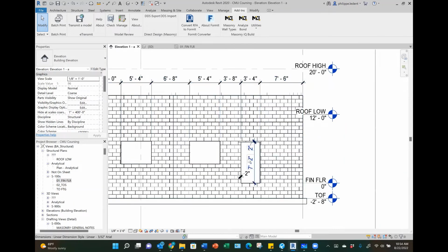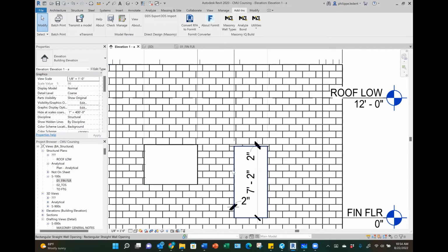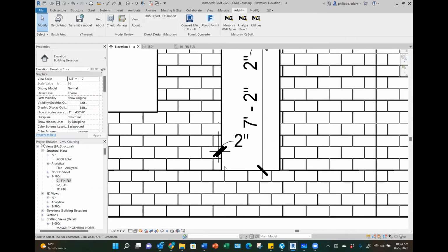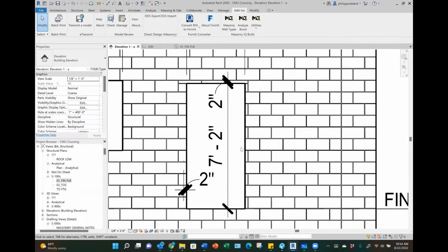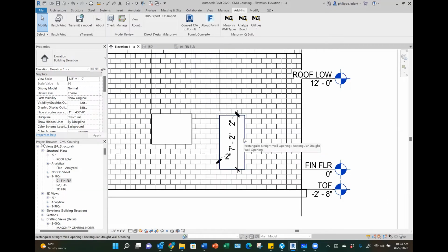Additionally, I had moved this door specifically to show you the impact of overall dimensioning. I offset it from this window 3 foot 8 inches, which looks like a modular dimension with that 8-inch number. However, if we look at this door, they would have to cut all these units on both sides of our door in this case. And again, we run into that same issue where on the right-hand side, we have a very, very small piece of a unit to accommodate that overall dimension of our wall.